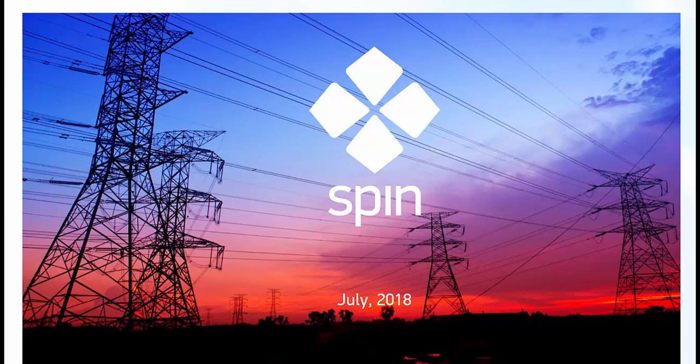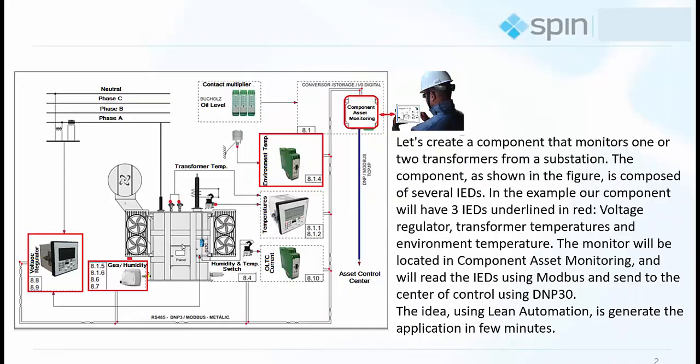Let's create a component that monitors one or two substation transformers. The component, as shown in the figure, is composed of several IEDs. In the example, our component will have 3 IEDs wrapped in red rectangles: voltage regulator, transformers temperatures and environment temperature. The monitor will be located in component asset monitoring, and it will read the transformer monitoring points belonging to the IEDs, and send them to the control center via a DNP 3.0 gateway.